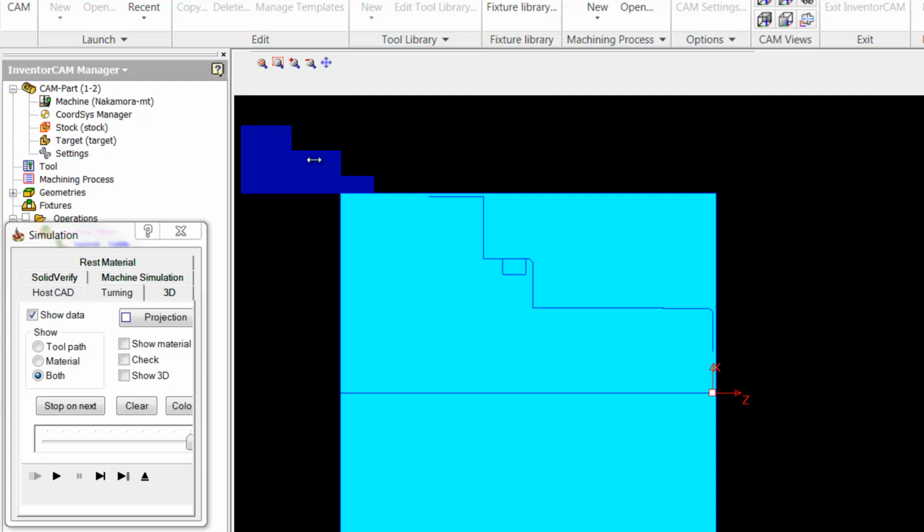If we look at our simulation using the turning option, you'll see that the tool goes in and actually zigzags its way in the ramping fashion, thereby also having the option of changing the point of contact on the tool itself as it zigzags its way down to the bottom. And then, of course, it does its finish step to complete this.